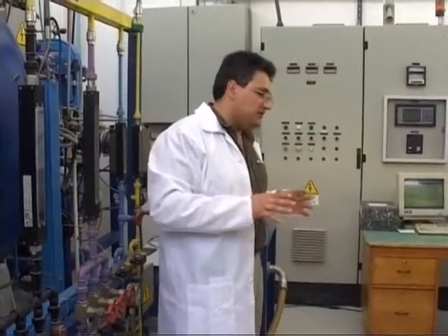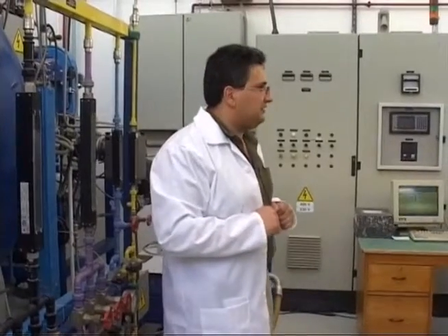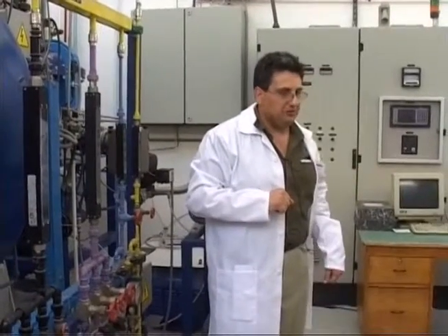Gas nitriding does not affect these surfaces in any case, because in this case we just heat the components in the presence of ammonia, which dissociates, thereby liberating nascent nitrogen. Nascent nitrogen is important for nitriding because single nitrogen atoms are small enough to penetrate inside the components or the surface layers of the components.